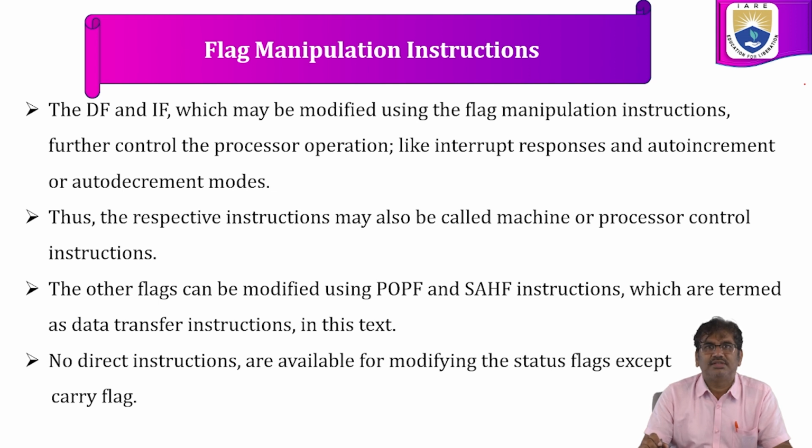The other flags can be modified using PUSHF or SAHF instructions, which are termed data transfer instructions. No direct instructions are available for modifying the status flags except the carry flag.